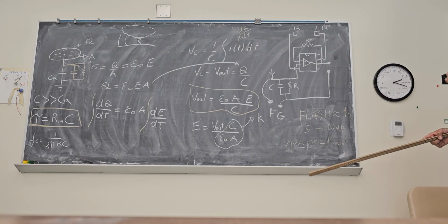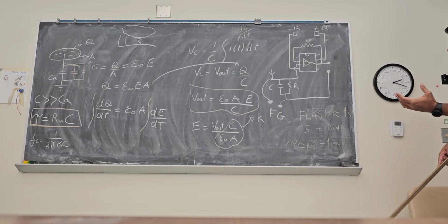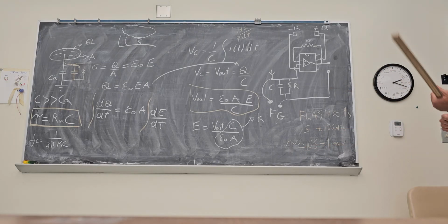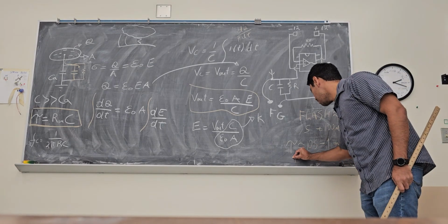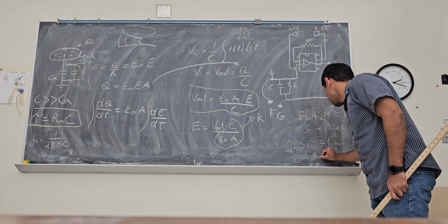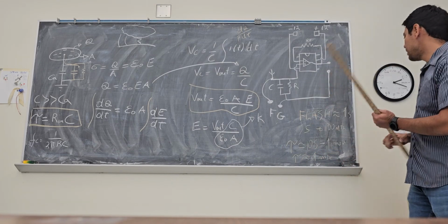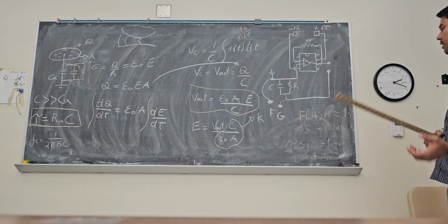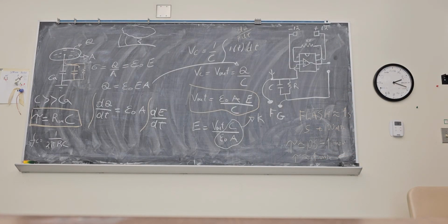If I'm interested in measuring the electric field change for a single stroke, probably a decay time constant of 1 millisecond is okay. So 1 millisecond is 10 times greater than 100 microseconds. We can convert this to frequency and get the same feeling, but looking at the decay time constant is the same thing. Questions?